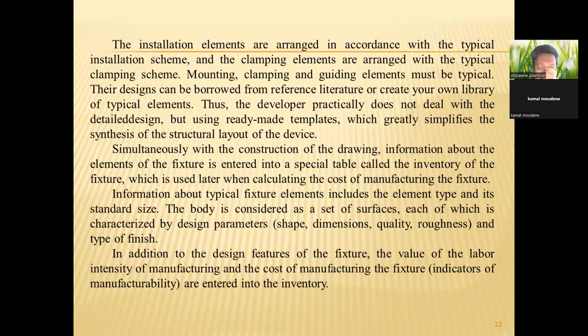Simultaneously with the construction of the drawing, information about the elements of the fixture is entered into a special table called the inventory of the fixture, which is used later when calculating the cost of manufacturing the fixture. Information about typical fixture elements includes the element type and its standard size.